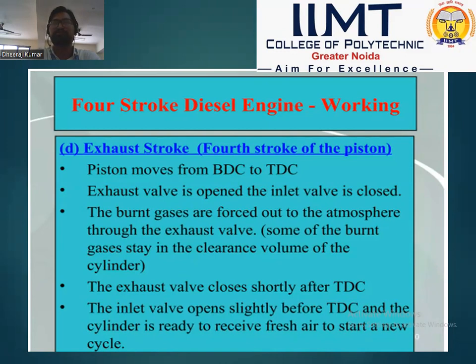The exhaust valve is open, and hot gases escape through it. At the end of the exhaust stroke, the inlet valve partially opens, so fresh air comes inside the cylinder. This is the working of a four-stroke diesel engine.